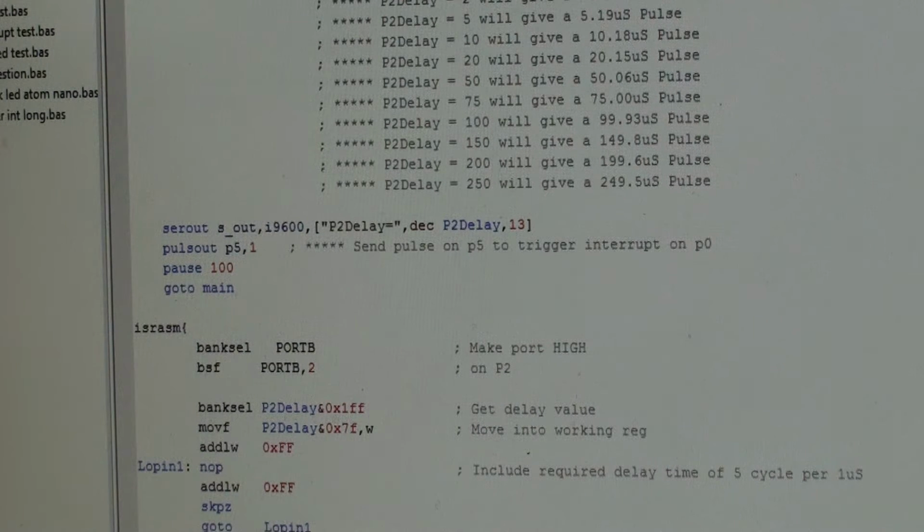Now when this program runs, effectively this interrupt will just be self-contained and the main loop will be going round. There will be a point, because you're delaying in the interrupt, where the interrupt's actually holding up the main program, and at the moment there's not a lot going on in there, but where it will cause a problem is with the serial out routine, because this serial out actually relies on software delays. It's a software serial port, not a hardware driven UART. So when we get to a higher frequency on the input, you'll notice that this actually will start to corrupt.